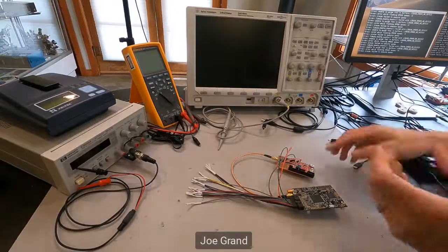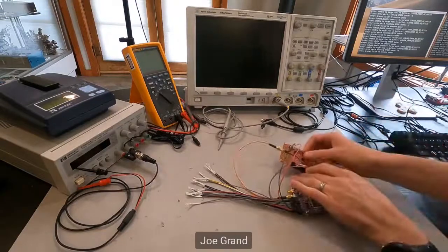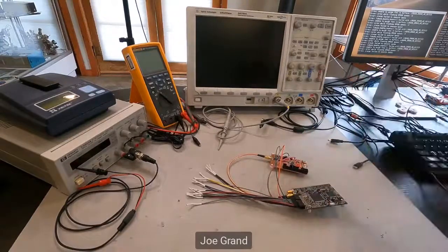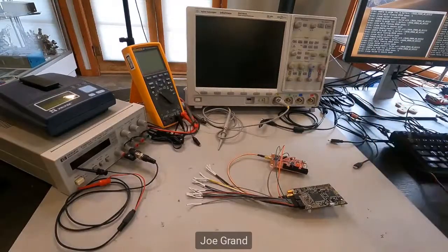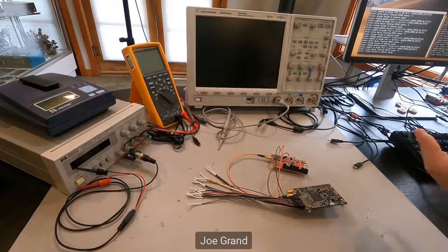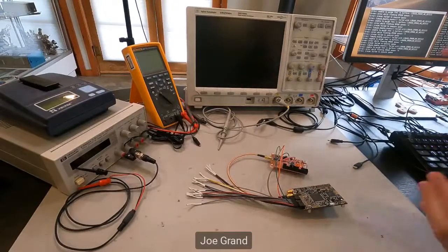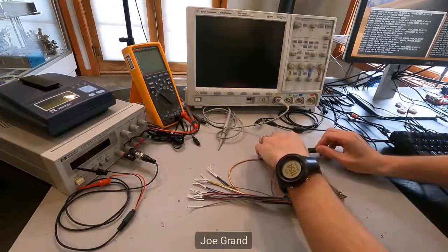Because as the boot ROM in the chip loads up, it reads the state of a register. There's 4 valid values for this particular chip. It's an LPC 1114, and a lot of the LPC family is also vulnerable. If you can glitch that, those 4 values are stored in a 32-bit register, which is 2 to the 32, right? There's 4 billion possibilities and only 4 valid ones. So if we can glitch that at just the right time and skip over that check, all we have to do is be one of those other 4 billion, and it's going to let us read the code. So I'm going to power up this board.